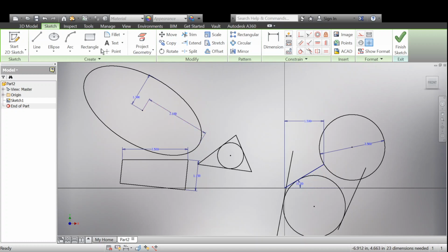So let's say that I did this. Go to rectangle, please, and choose the rectangle that I'm hovering over, the 2-point center rectangle. It's the third option down. Now, click on the 2-point center. There may come a time where the center of a circle needs to line up with the center of a rectangle, and that's when you might use this. So go over to one of your circles and click to start at the center, and then move away from that. It will build the rectangle outward from the center, and it'll lock those centers together.